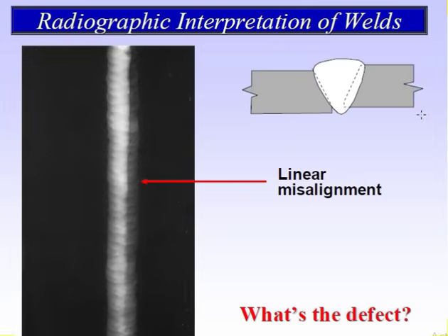You see the misalignment, linear misalignment. You see this is the level, but you can see the fitter has not done the joint properly. So this is misalignment. If there is a misalignment, definitely there should be a density difference. You can see the density difference, linear misalignment.